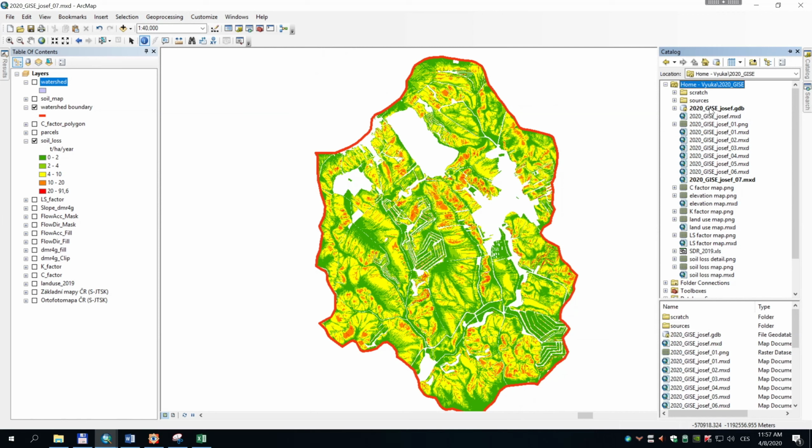So when I choose my geodatabase, the content of the geodatabase and all layers are visible downstairs. I drag down and find in my database a layer called watershed, and I just take it and drag it into the project. You can see this small plus close to my cursor.